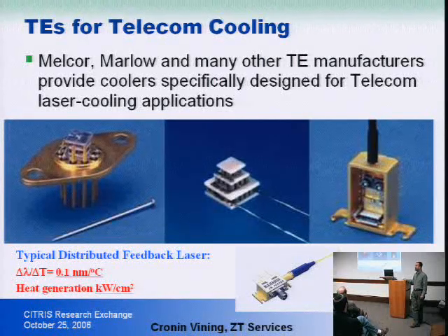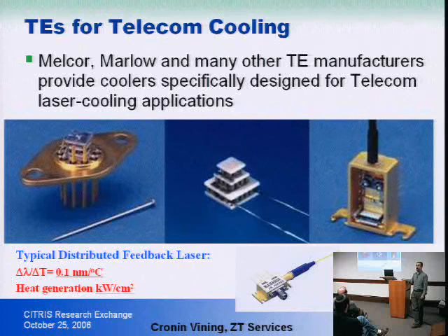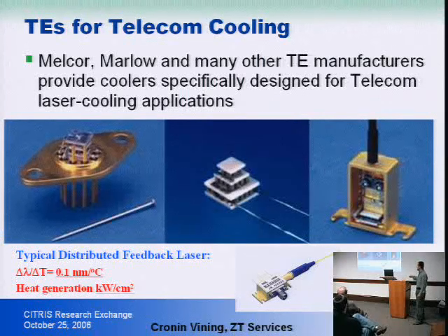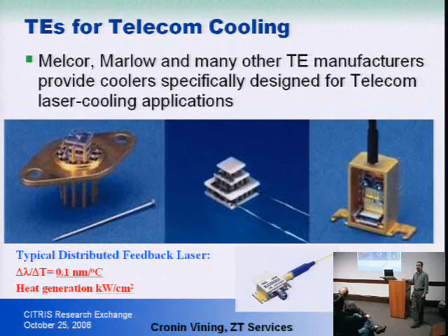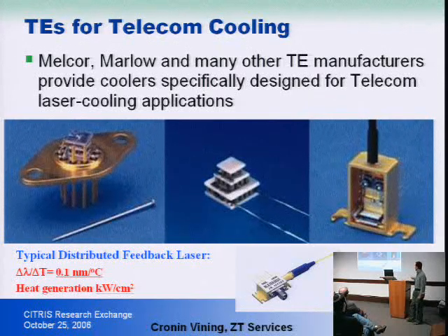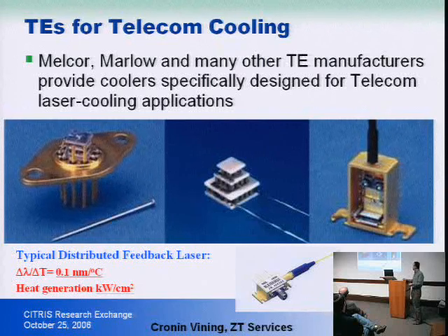And that's perfect for a laser diode, which is kind of shown here. Basically, fiber optic communication has been very successful by sending lots of data at very fast rates over long distances. But even the most stable laser that we have, the distributed feedback laser, has a wavelength sensitivity such that if you change the temperature of the laser by a couple of degrees, the whole fiber optic system will not work well. So each of these long-haul communication lasers is temperature stabilized to within a degree, and this is done using small thermoelectric coolers.